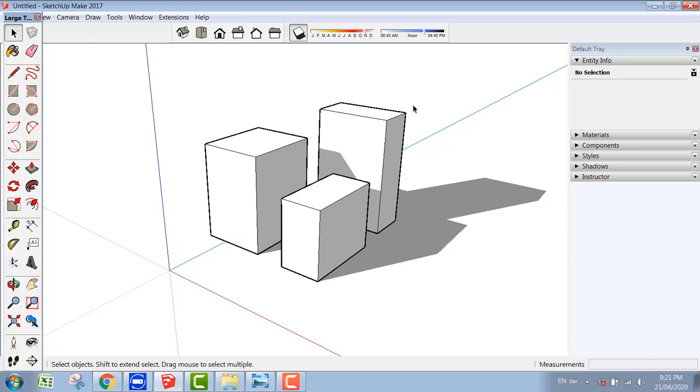So even if I open a window as small as that, anything that has been cut will be selected. But if I open a window from left to right, it will only select an object that is completely inside my window, you see.